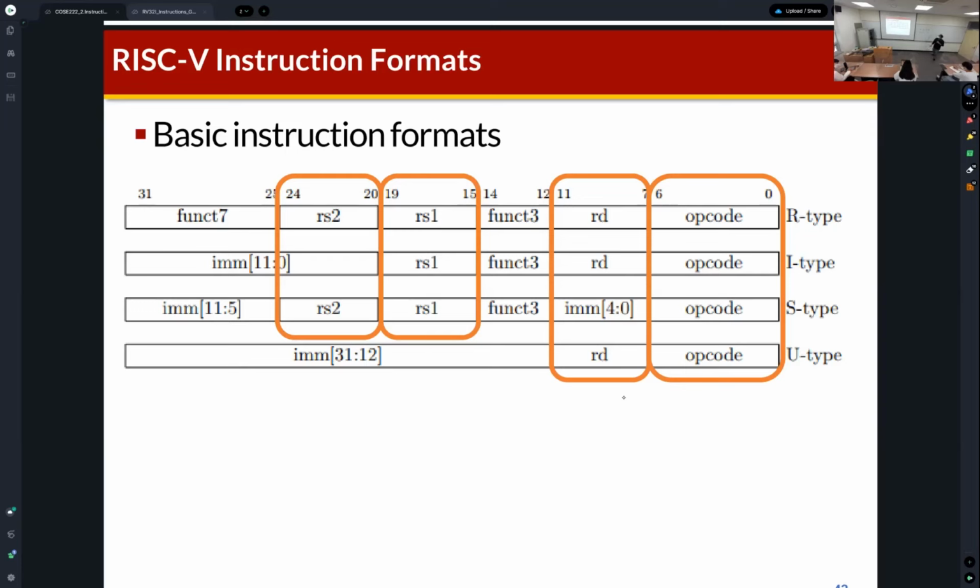So if you see this instruction format, you can find the RD is 5 bits of the instruction word. RS1 is here, RS2 is here. So with these 15 bits, we can represent the RD, RS1, and RS2. Which means with the remaining fields, like the opcode is here, and then funct3, and then funct7, we can represent the add. Okay? You understand? Then how about the I-type instruction?